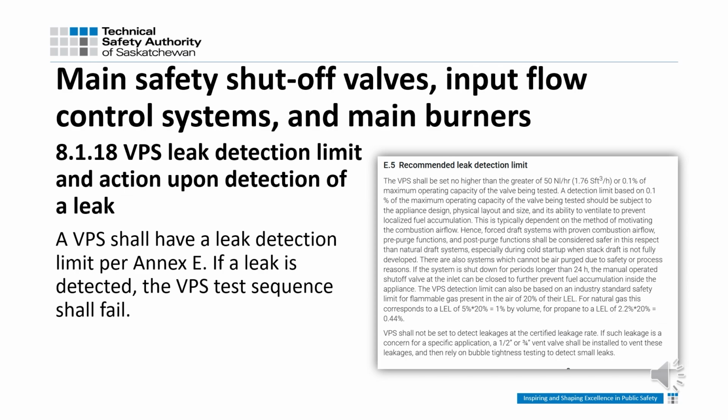8.1.18 VPS leak detection limit and action upon detection of leak. A valve proving system, or VPS, shall have a leak detection limit as per Annex E. If a leak is detected, the VPS test sequence shall fail. E5 gives the recommended leak detection limits.